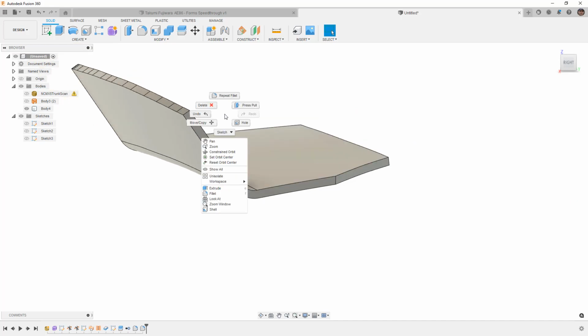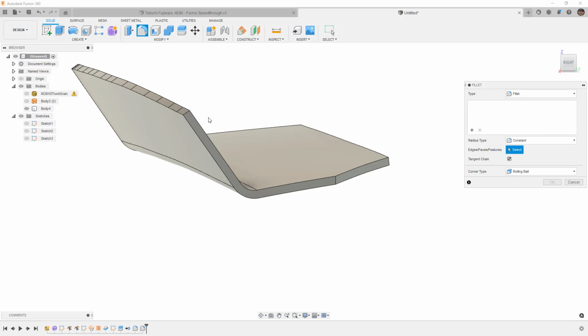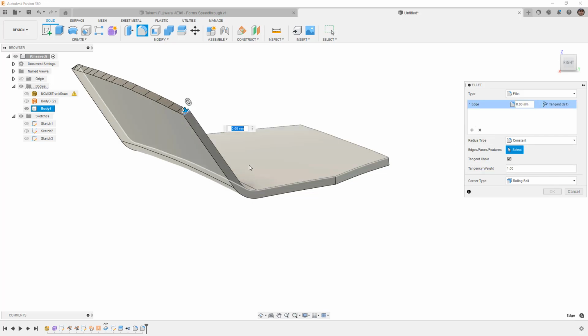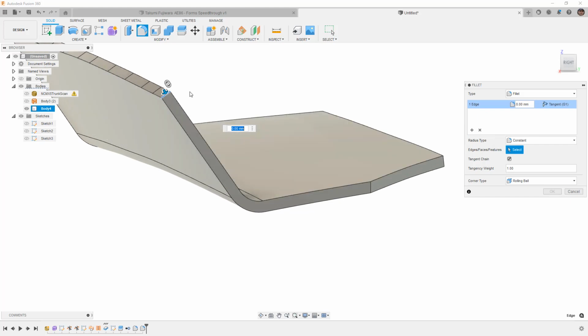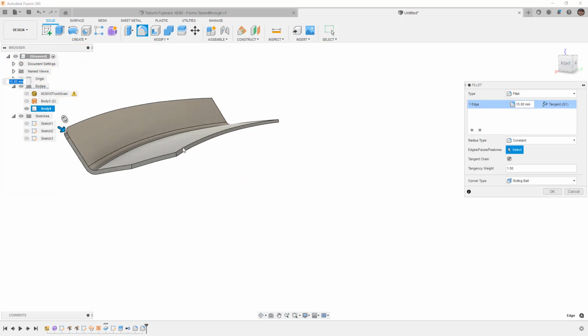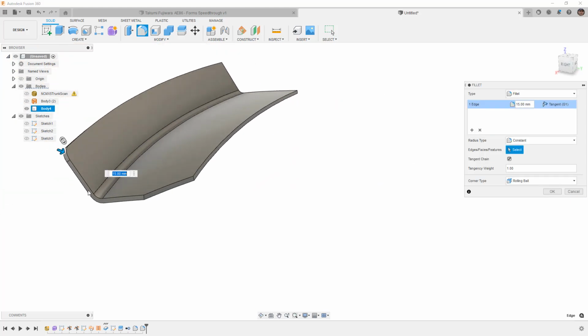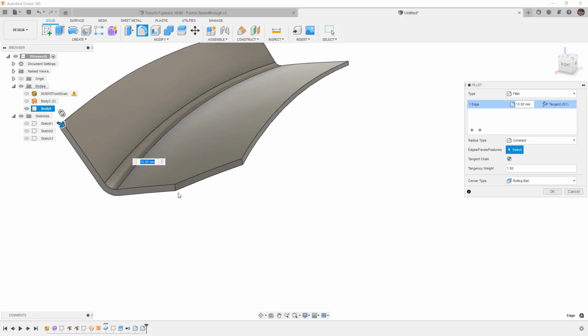And I'm going to try to fillet it one more time. I do want to note that with the fillet tool, you can add additional selection sets. If they're dealing with different edges, then generally that works okay, but sometimes you have to be careful. This one's going to get tricky. If we go any further than this edge, it's going to fail. So we just need to pick something that visually looks okay. I'm going to hold down Control, and I'm going to select these two corners as well and apply the same fillet to those and say okay.